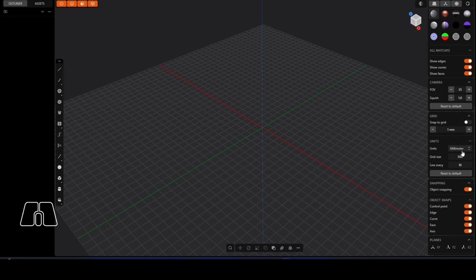Depending on what you're doing, what your intentions are, adjust your metrics, so your units set up accordingly. So for example, if it's tabletop, you might want to be in millimeters, you might want to be in cm, or for Unreal, definitely cm. So 1 Unreal unit is 1 cm. So just keep that in mind.